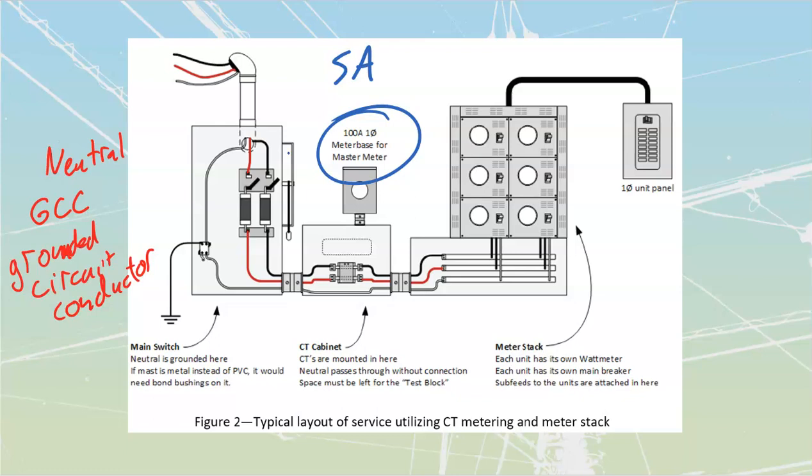They're going to actually feed it with number 10 gauge wires. They don't need much because they're only working with a maximum of 5 amps, but they need to have a place where they can mount that meter in, a standard meter socket, and that they can seal, etc. So that's going to be mounted over top of there with a short chunk of pipe.